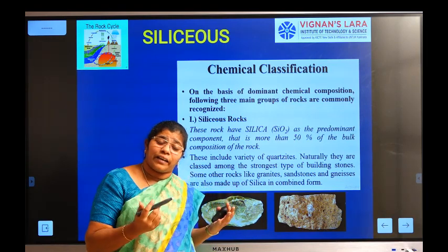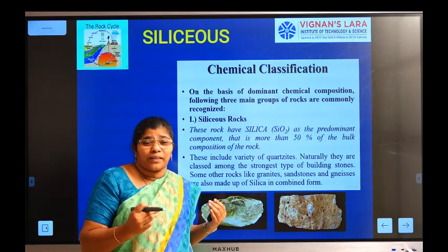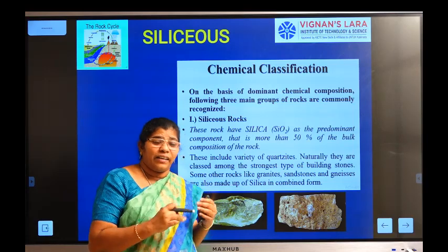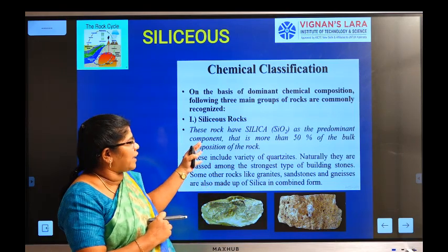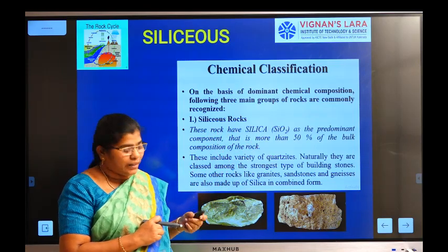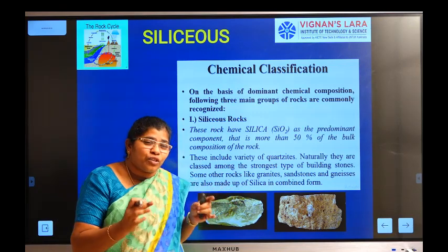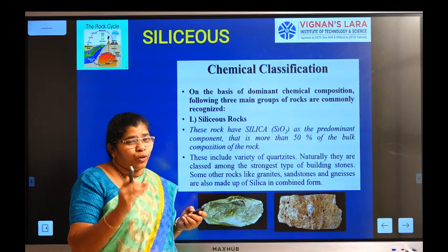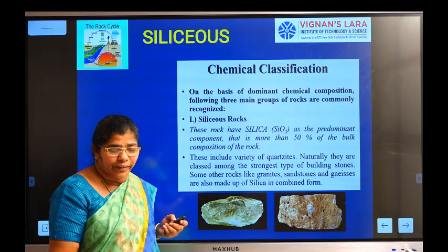If you think about which particle has more silica content, immediately you should be able to say sand is having more silica. A very good quality of sand. Soil is having a very good silica content, right? So the silica which is more than 50%, around 70 to 80%, will be available in this rock. The granite and sandstone, which are mostly used for construction purposes, will be having some silica content. As I told you, a good example is having around 80 to 90% of the silica, right?